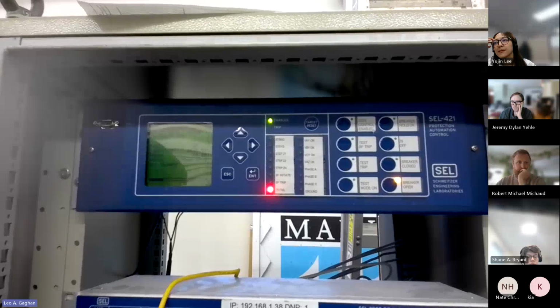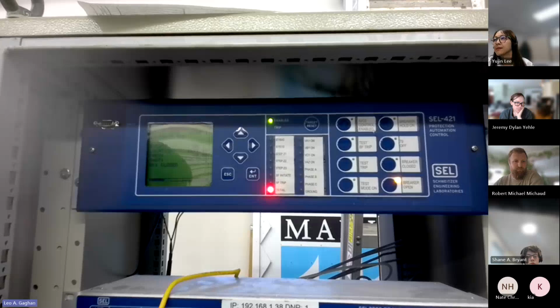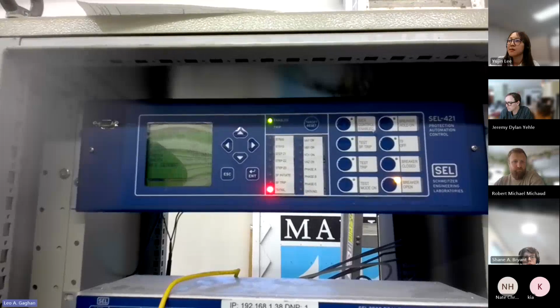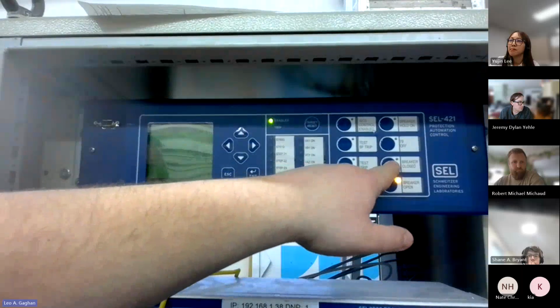So we can see here, we push button 8 for a full second. Breaker is closed, because no point in opening a breaker if it's not closed. And we're not in hold, right? We've got that safety function. And it's not in control switch mode, then we'll close that breaker. The flip-flop down here, everything is the same except we are in control switch mode, so it should do the same thing. So we'll run through this. Right now, the breaker is open. We're in relay mode. Let's close it.